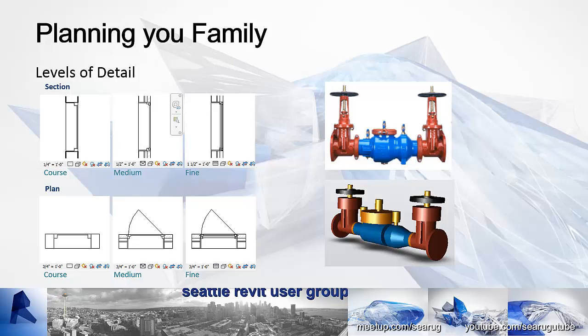So we're not just building a 3D model and having that model show up in plan, elevation, section, ceiling plan, we're actually building multiple representations of it combined into one family. The 3D model only shows up when you're looking in a 3D view. This is also going to improve performance factors.